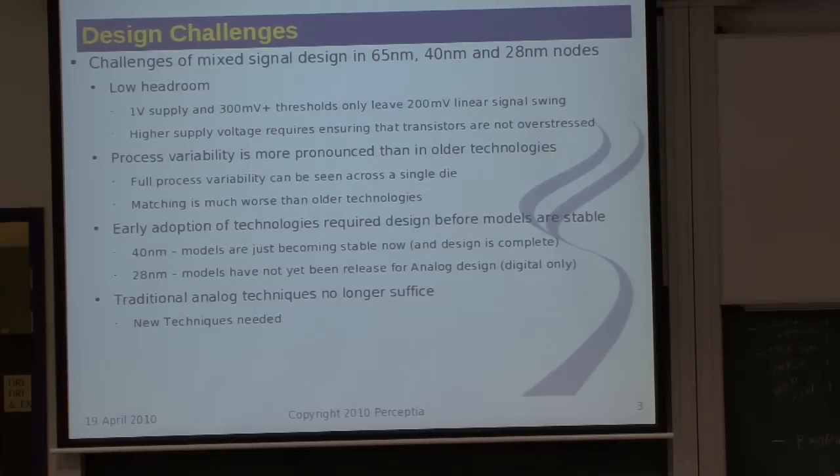So in a digital context, while talking about the timing, the delay through, say, some specific logic gate, we can't just call that one number. If we've got transistors that are slightly faster, then that delay's gone down. Great, we can run it faster. If we got another one, it might run slightly slower. Now our timing's stuffed. So we have to make some assumptions based on the slowest we're reasonably going to see. And then every chip is tested the moment it comes out, and they throw away 10 or 20% of them for errors that can't be controlled.